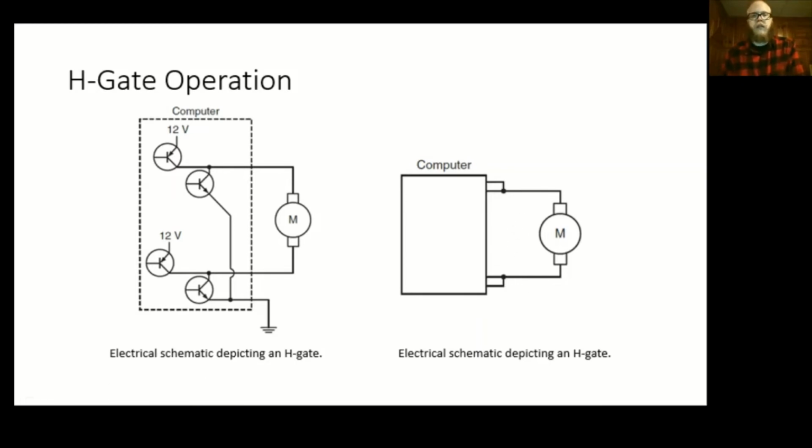No. Well, maybe that's because it's all the way up or all the way down, so I just tried to roll it all the way up. It's all the way up. I didn't know, so I'll reverse my polarity. So then I put ground and power. Oh, now it moves. I've just proven that my wires are good, my motor's good, and even that my input was good because I had looked at this with a scan tool to see if I was getting the input. So maybe one of the drivers, one of the little transistors built into the computer itself is burned up. Well, then computer time, we actually get to replace it.